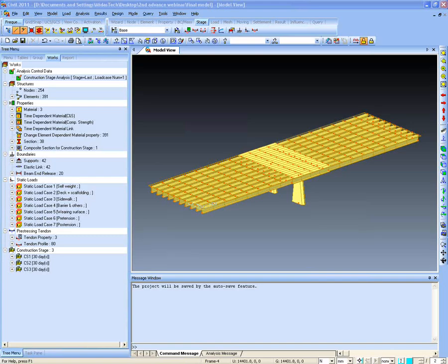So there is another question by Mr. Johar. He wants to ask, have the seismic forces been involved in construction stages? If you model the seismic forces as nodal loads or element beam loads in the desired direction, you can apply those loads in the construction stages, but you cannot perform the time history analysis or the dynamic analysis in the construction stages. But the other way is to do the time history analysis or response spectrum dynamic analysis for a construction stage by running the model till that stage only, and then in the post CS mode you can see the effects due to the time history.